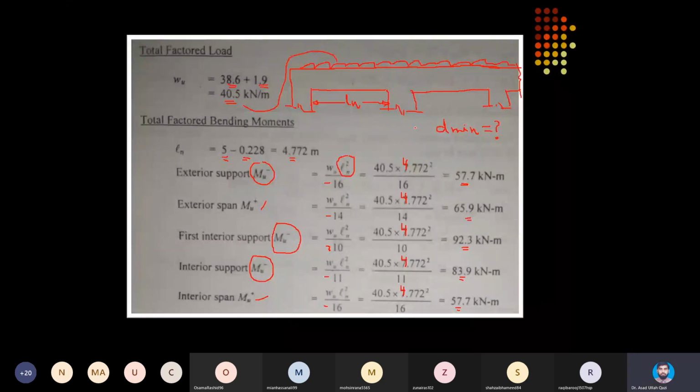So then I have to go doubly at those portions where D becomes less than D minimum. So it is always preferred to scan the moment demands and out of them select the maximum moment to fix the depth of the beam.